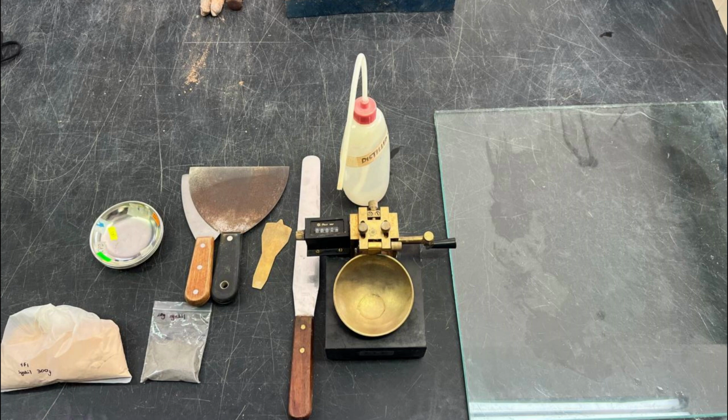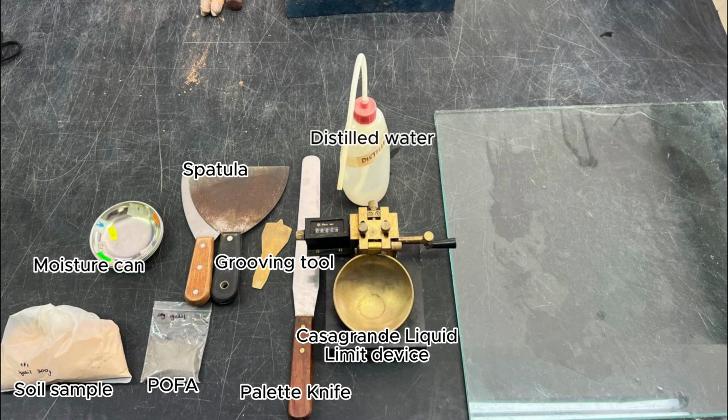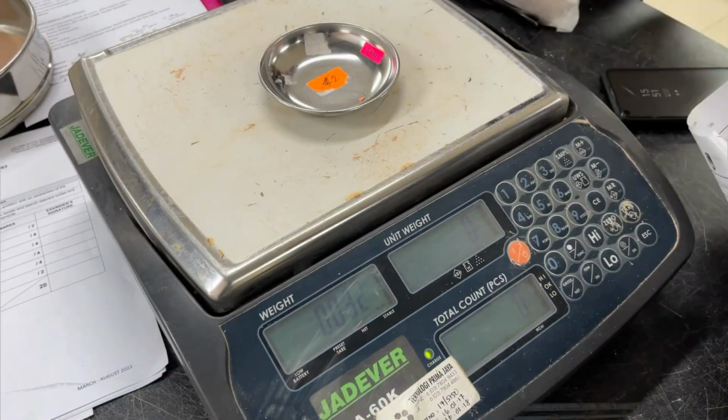Liquid limit Casagrande test. The apparatus and materials used in this test are 200 gram of soil sample, 12 gram of POFA, Casagrande liquid limit device, grooving tool, spatula and palette knives, moisture cans, wash bottle containing distilled water, weighing balance, glass plate, and drying oven.